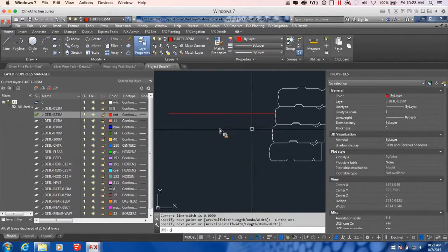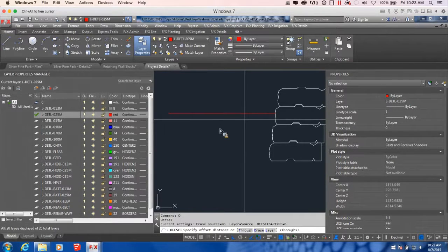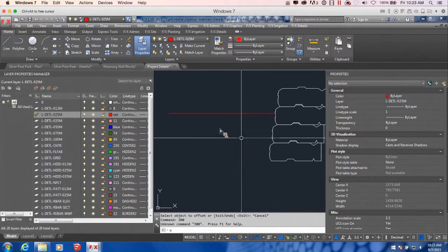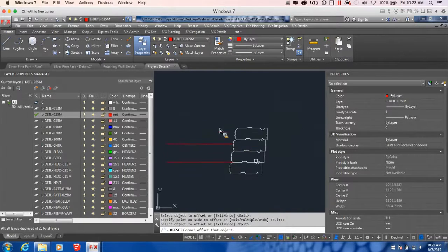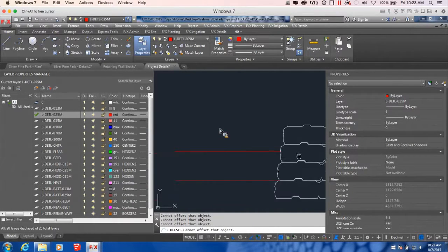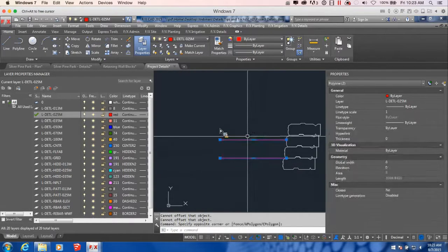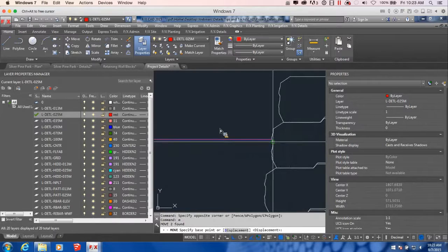And my playground, for the mulch, is going to be a mulch safety surface, so it's going to be 0.3 meter depth or a foot depth compacted. Sorry, I'm in millimeters, so that's 300. There we go. And I'm going to just adjust that a little bit so that the top of my playground goes right to that first step.